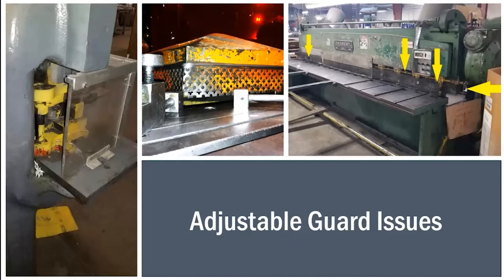This notcher in the middle, the guard's designed to go up and down to the thickness of the part being used, so you have an 1/8 inch gap, but it wasn't adjusted and is left up, and you have more than an 1/8 inch gap. Guard on the left here, this is an error in construction. It wasn't designed and built to fully restrict access. You can reach around the back to this little punch press.